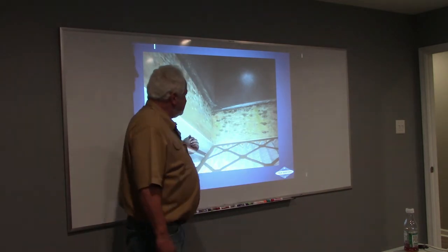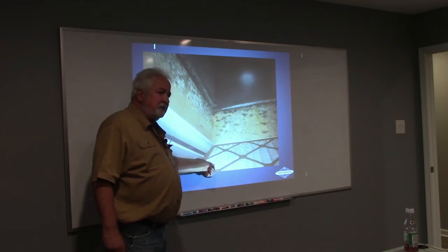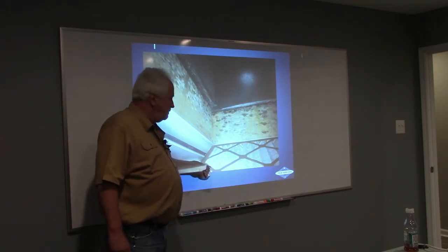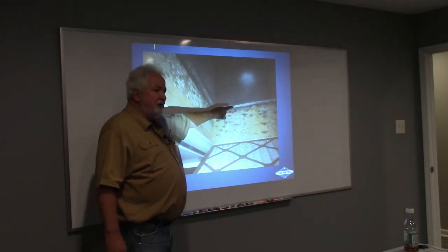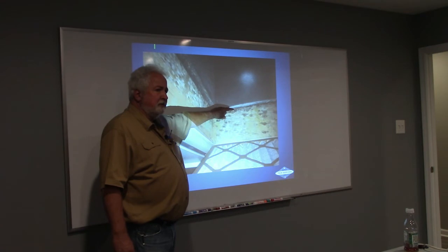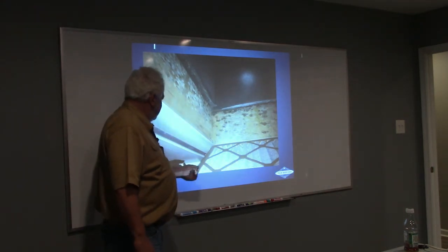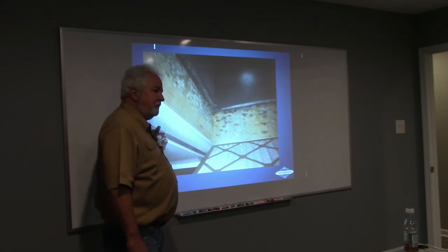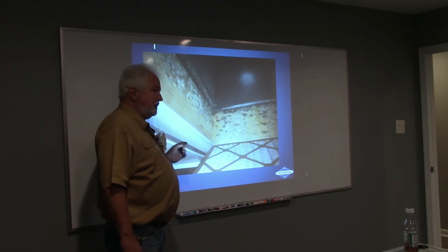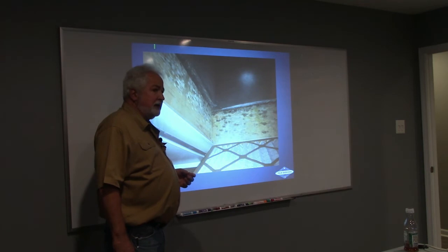If I've got moisture in a cool area, what's going to happen? Good. Let's make it even worse. Let's put in a really restrictive pleated filter and close that up. What's going to happen to the amount of air being pulled in there when it comes on? More. So much that it's even going to run around the filter on this right here. It was screaming at me where the problem was. The guy said, I can't get the moisture out of the house. Well, no, I guess not.